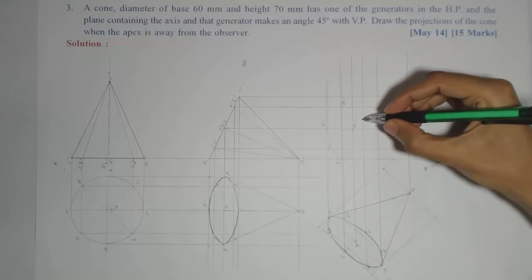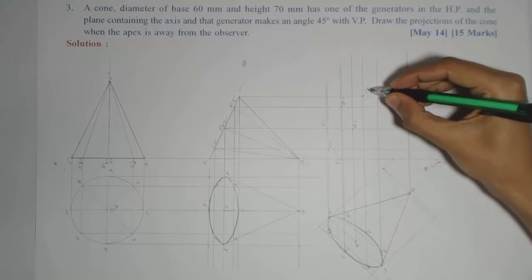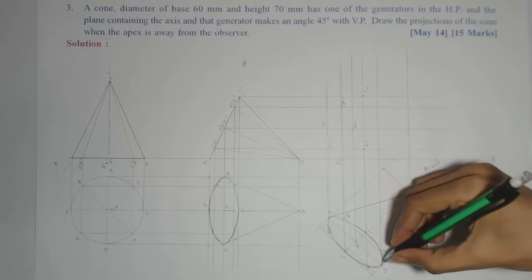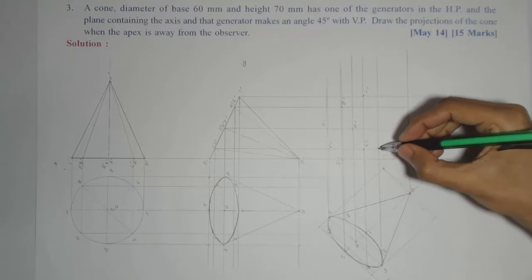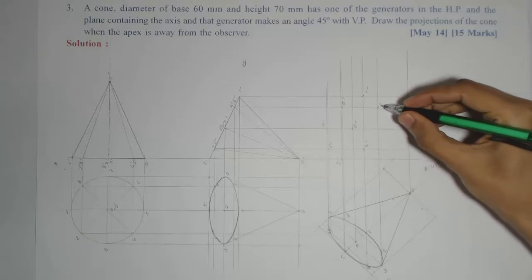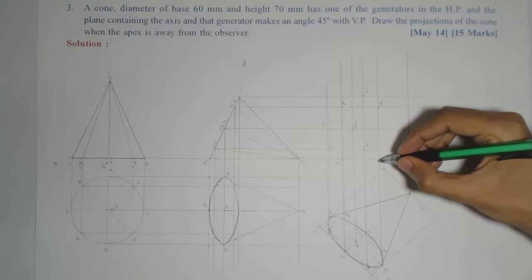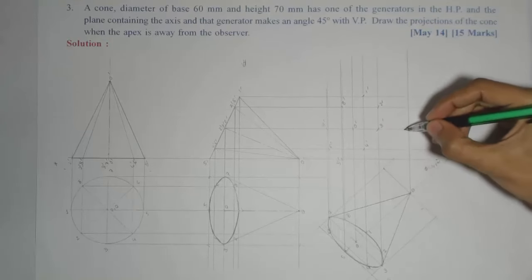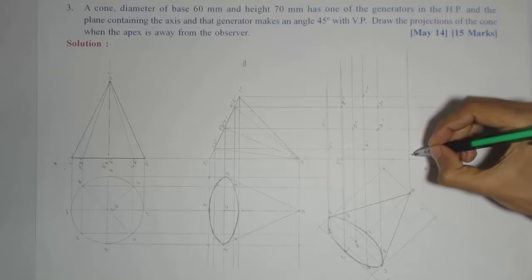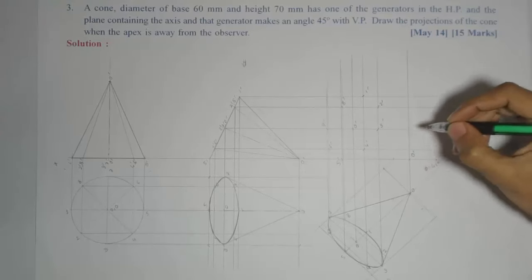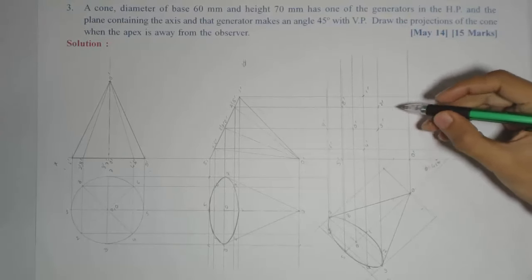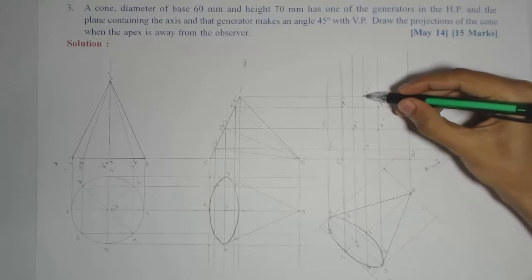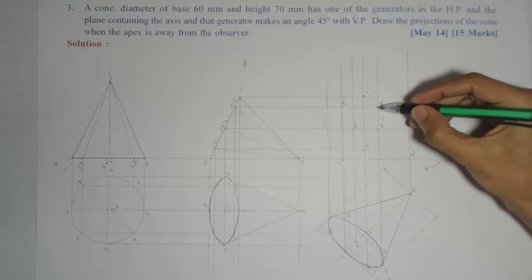Then 1 and 4 are on the same projector, so 1 is at the top, 1 dash, and 4 is here, 4 dash. Then 2 and 3 again on the same projector, so 2 is here and 3 is here. Now finally the apex is on the xy, 2 dash. Now we'll join 1 to 8 in sequence with smooth curve first,